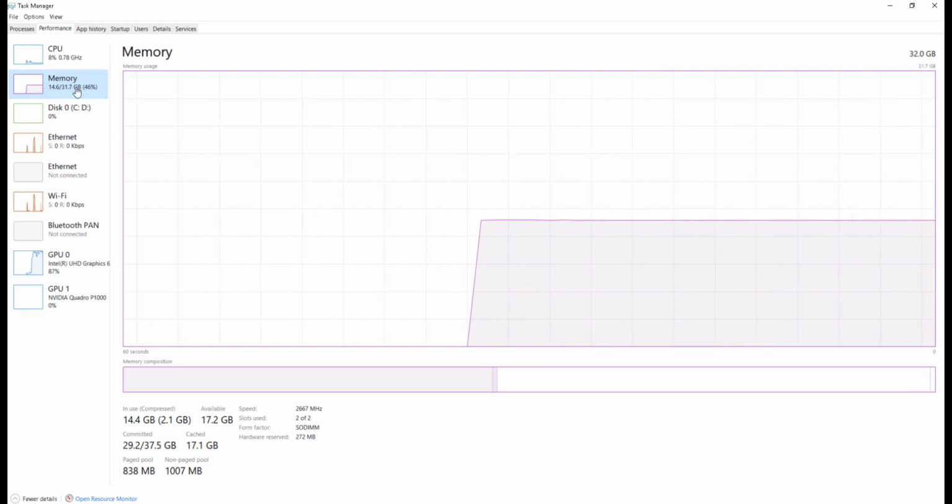And most of the time you also need to know that, without running any simulation on my machine, still 14.6 GB is already occupied by other software. You need to be careful here. The problem is that even though we say I have an 8 GB or 16 GB machine, a good amount of RAM may already be used by the OS and other applications. So if you are running out of memory, make sure you are closing all the unnecessary software. Close everything so that you can free up a lot of memory.